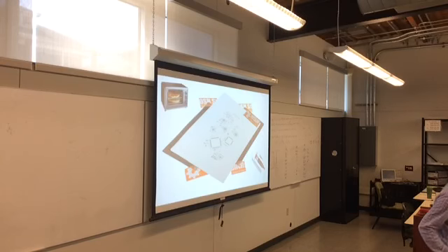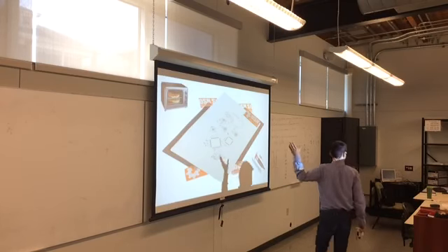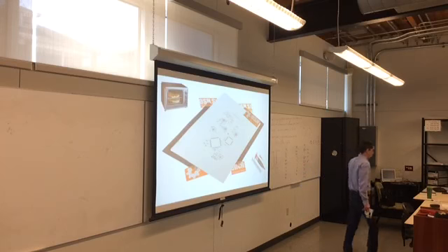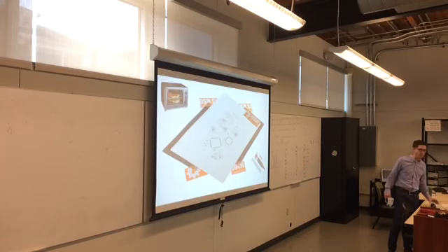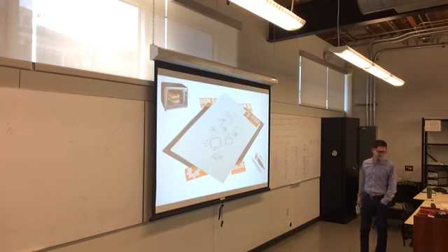A lot of things that you can buy from SparkFun, Adafruit, things like that, come with the schematic and the layout. So you can just take the schematic, import it into your schematic, and connect it up. The one thing I would do if you're doing that is always pay attention to the power lines and any sort of analog lines, because people design those intentionally.